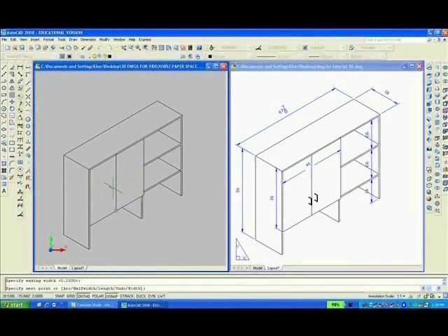That'll give us a heavy line. It's a polyline. And all I've got to do is copy that heavy polyline, hit the F5 key, and drag it over, find a spot that looks right. So the drawing essentially is done, okay.